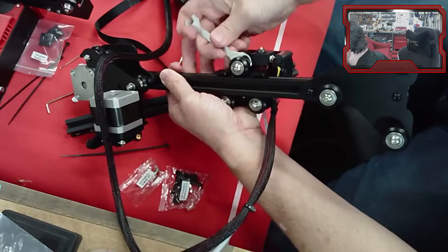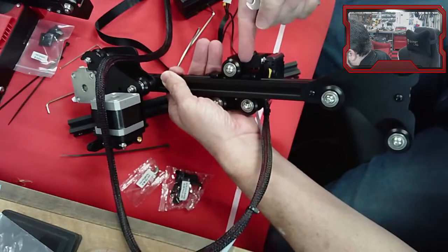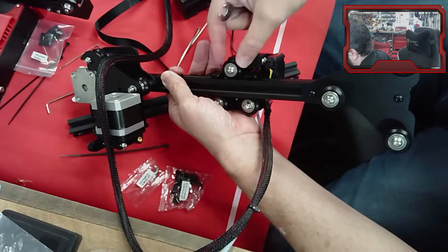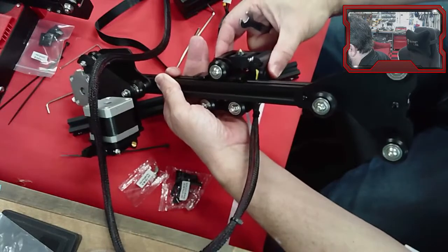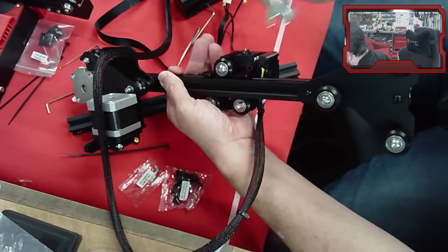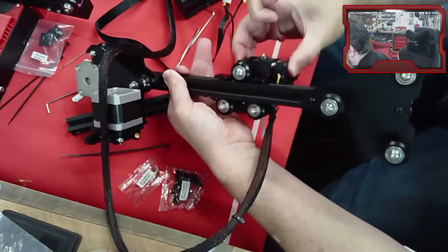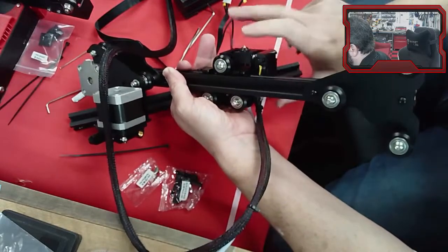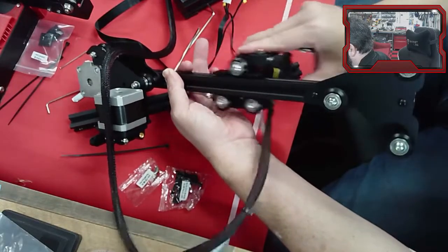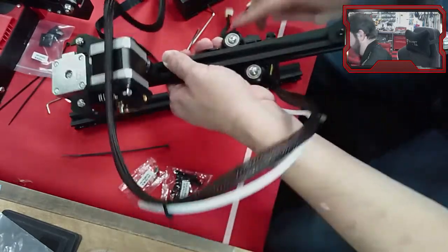They've actually got pretty tight tolerances, but turning this eccentric nut moves this wheel further away and closer in. So if this is shaky or wobbly or anything, then you adjust it until it's not super tight, but it moves freely and it doesn't rock back and forth. And this is pretty solid, and it moves pretty freely. So I'm going to go with that.